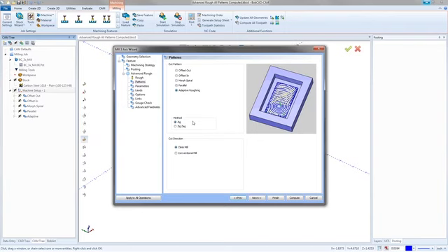So the next thing we're going to look at is adaptive roughing. Now, the adaptive roughing is the high-speed machining strategy. What you want to make sure you're doing with this one is just modifying how you're cutting. With most of these advanced roughs, if my norm is a 1/4 inch depth of cut and a 1/4 inch step over, so really a 50-50 depth of cut to step over, with the adaptive roughing, I'm going to go a little heavier on the depth of cut, but a little easier on my step over.